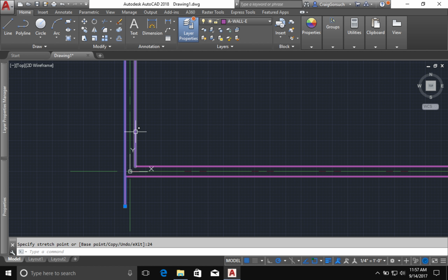So now what I'm going to do that's a little different is, there's no command that's active. I'm going to select that inside line for the vertical wall. I'm going to hold my mouse over this endpoint. And then I'm going to move my mouse down in the menu that shows up and says lengthen. So I click on that. Now it doesn't matter what the X value is for my line. It keeps the angle of the line identical, so I can actually click on that endpoint of the adjacent line, and you can see the value immediately above still says 2'8". So if I left click right now, then those lines are in alignment.